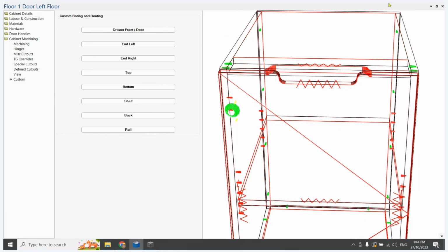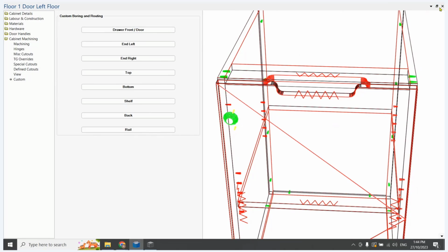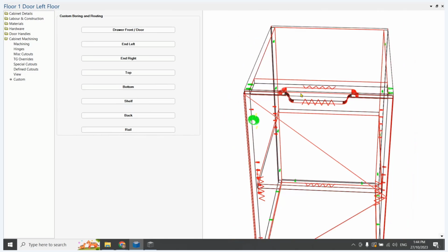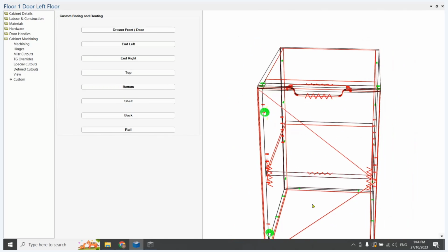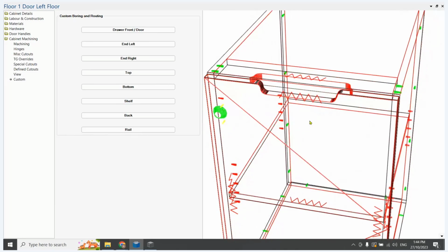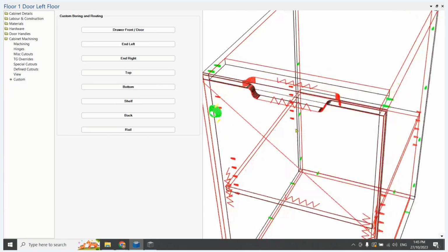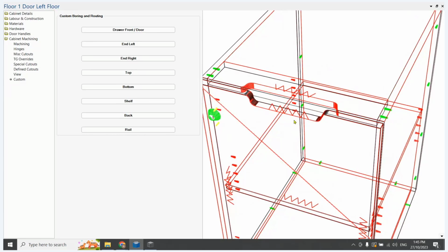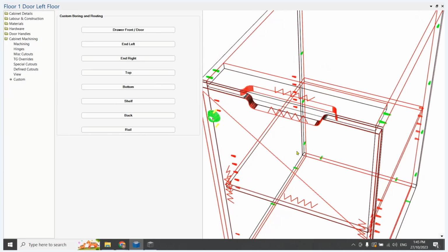Now, if you're doing an entire job with this cutout, you only want to apply to base cabinets. It's not going to apply to a wall cabinet because you just have your doors hang down and use your finger pull that way. Tall cabinets, you might apply your own routing in the middle of the door, or you might still put handles or push to opens, tip-ons. So you really only want this to apply to base cabinet, drawer fronts, and doors.